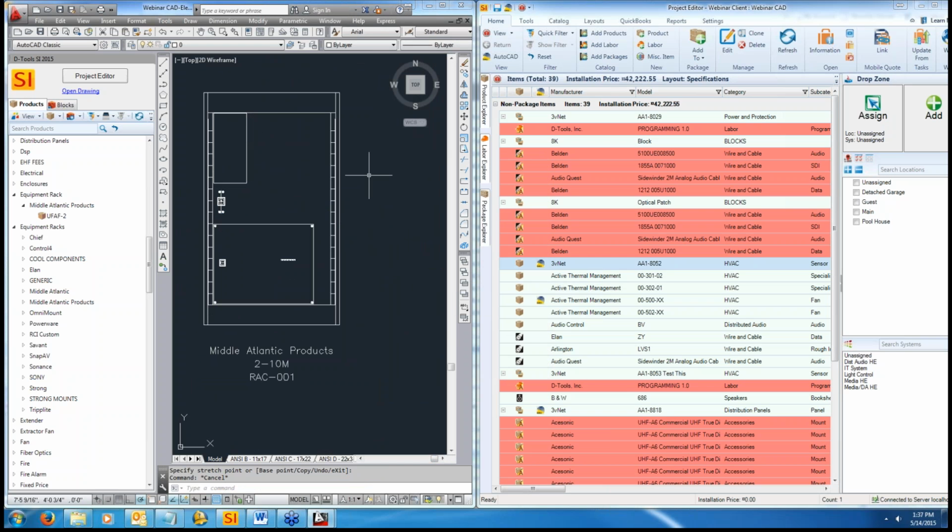you can again build elevations just like in Visio. Again, one thing to keep in mind is that you can't resize these shapes because they pull directly from the specs. So the only way to resize them is to change the specifications, which would kind of give you false information or would defeat the point of the elevation.